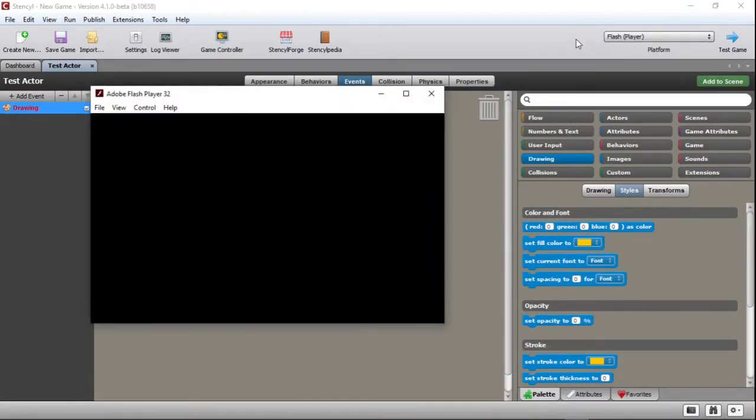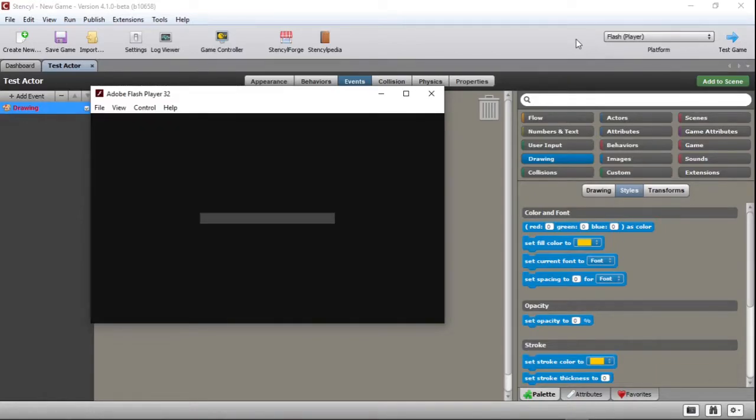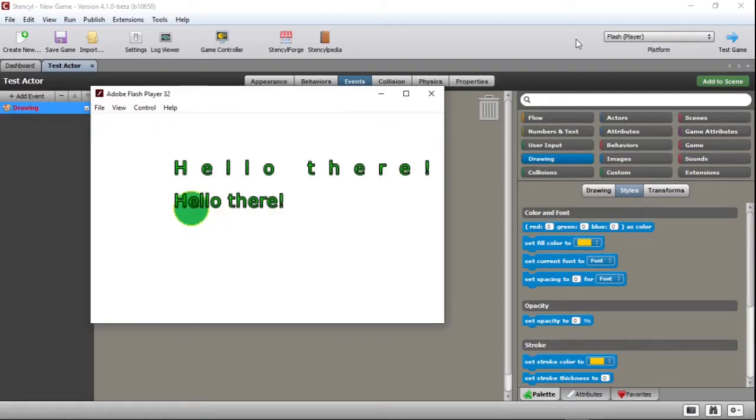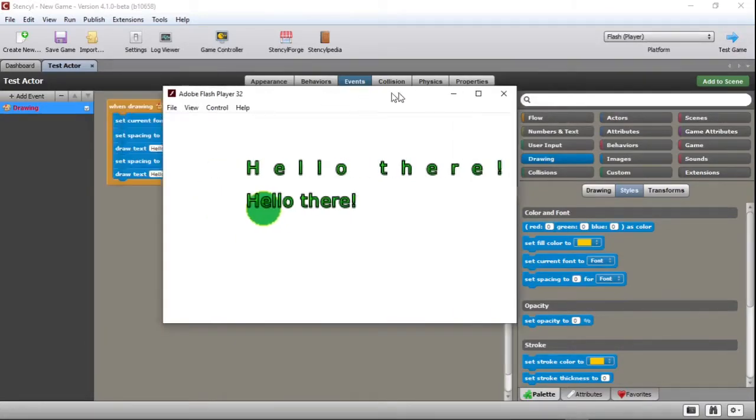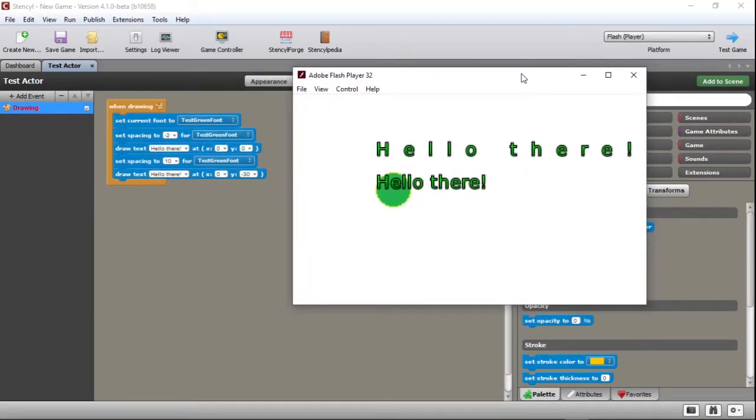With all that in mind, always set the style blocks first. A text drawing without a font set may grab a font from another drawing on the scene and have undesired results, so make a habit of always setting the necessary styles before the drawing.